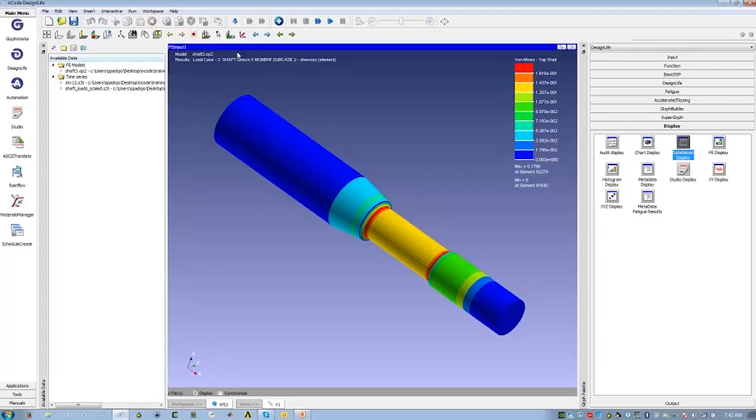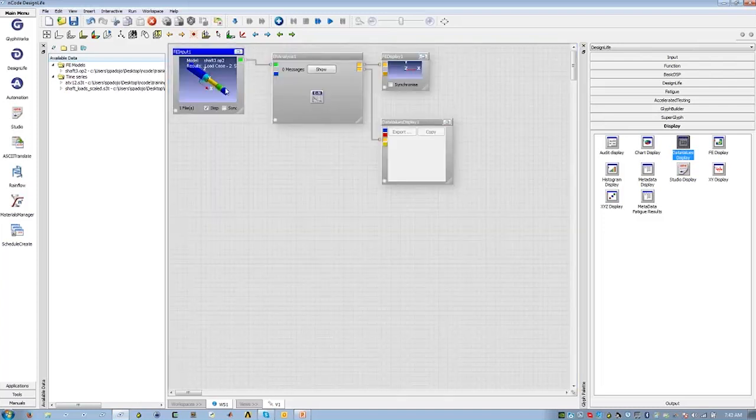I know that my vertical load is applied in this positive z direction, so I went out into the field and recorded the loads that were occurring over time in that positive z direction. At the same time, I recorded the torque loads that were occurring. That recorded data has been saved in this DAC file, or this time series file here.